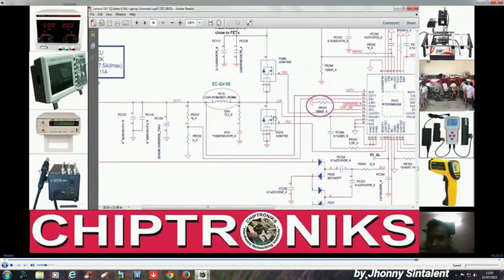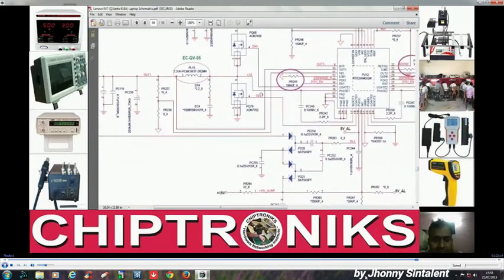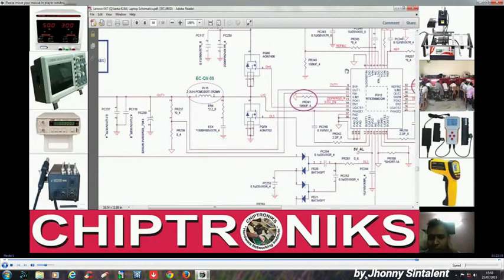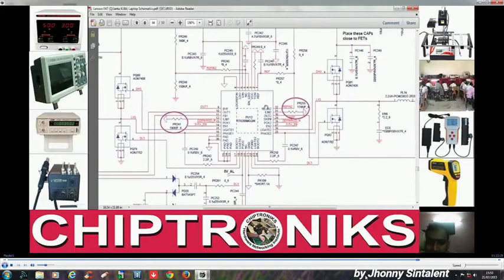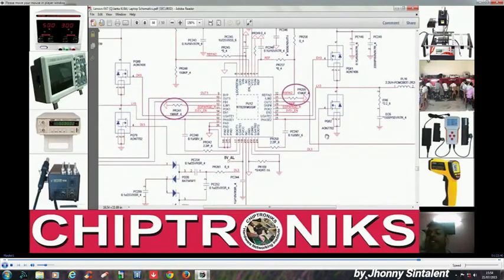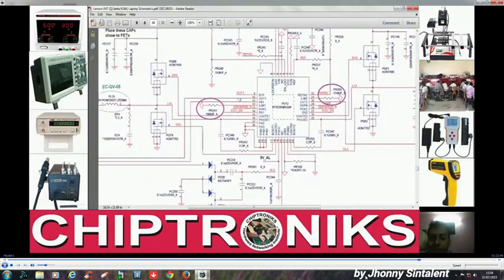So as we have already spoken, this regulator operates in two ways. This part is working in adjustable mode because the feedback is connected, right? FB1 is connected, whereas here the REFIN2 feedback is connected to 5V_AL, that is, it is connected to the VCC. If it's connected to VCC, then it will work as fixed, right? It will work as fixed.